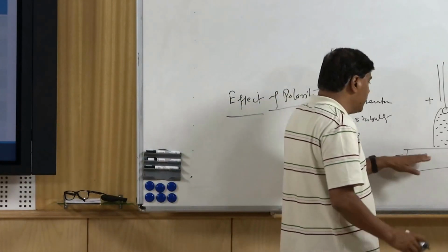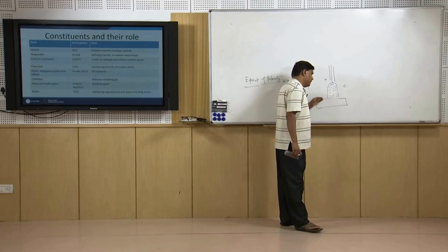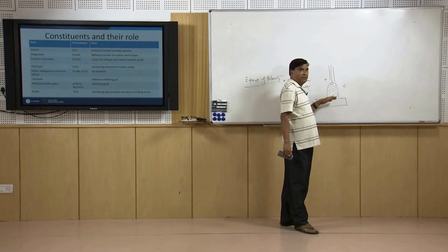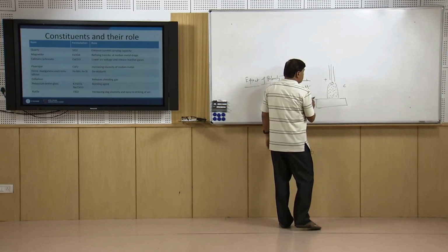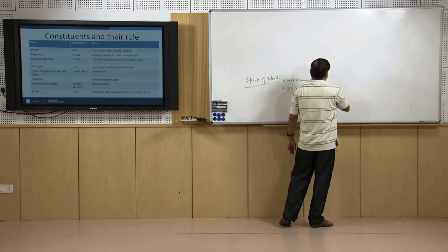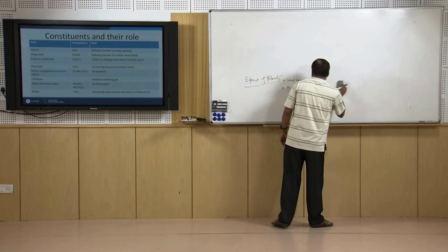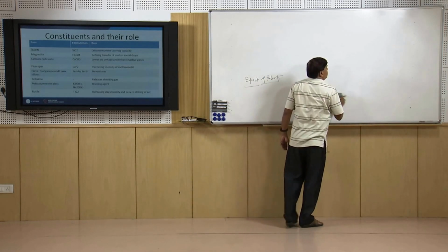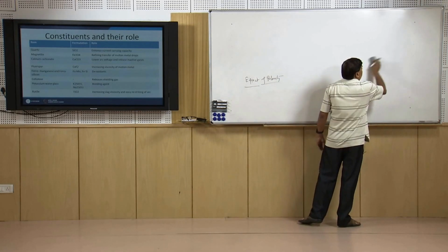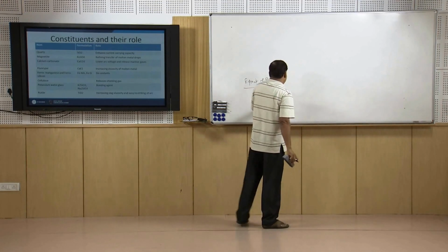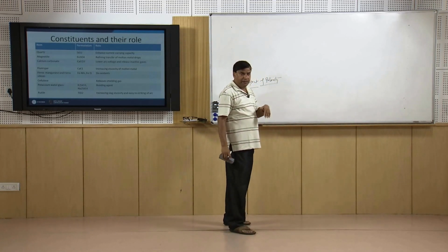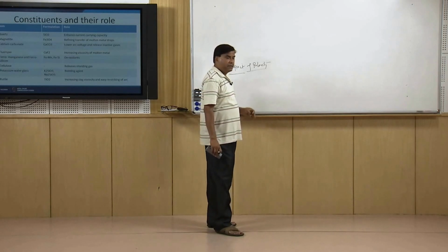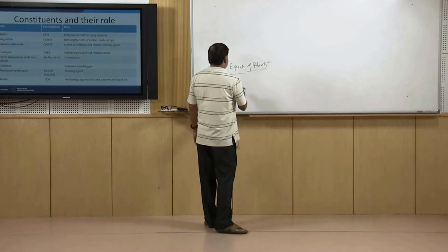So, the change in polarity, especially where the workpiece is expected to emit the electrons, and if it does not have very good electron emitting capability, will lead to poor stability of the arc. If the electrode is designed to have good electron emission, then changing the polarity from straight polarity to reverse polarity can cause a problem of arc stability due to the poor electron emission of the workpiece.